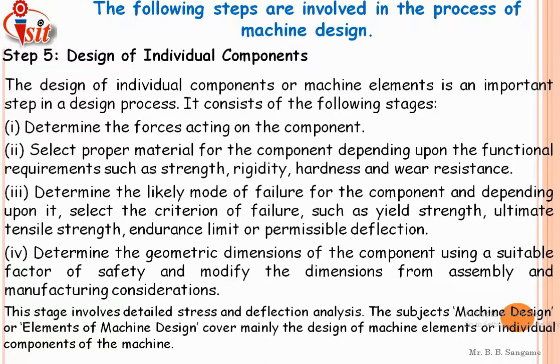The first is determining the forces acting on the element. Second, selection of the proper material depending upon the functional requirement of that element. Third step, determining the mode of failure. That means you have to determine which type of stresses are induced in the component and what is the nature of that stress due to which that component will fail. And by considering that failure stress, we have to design the component.